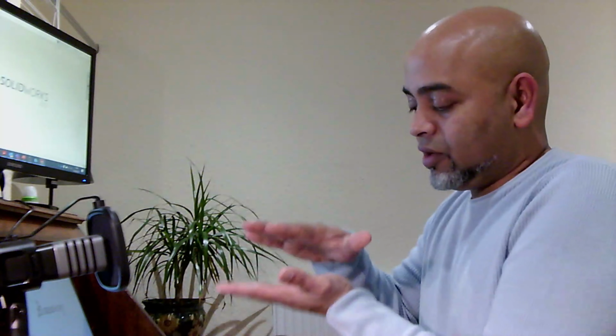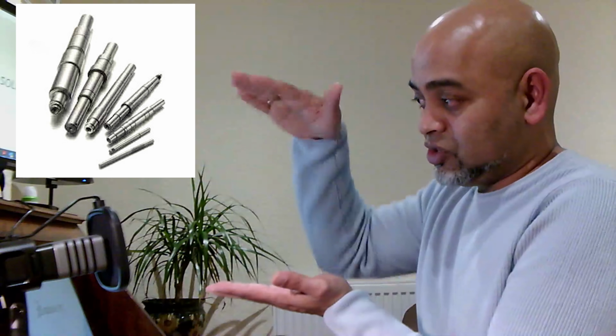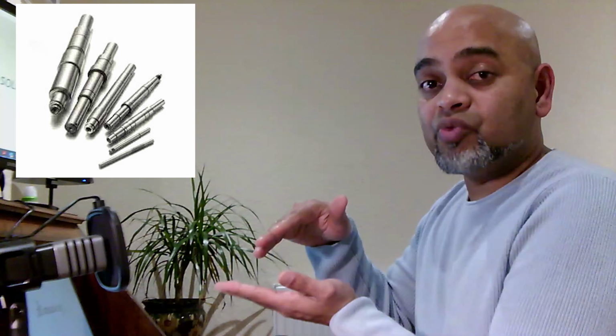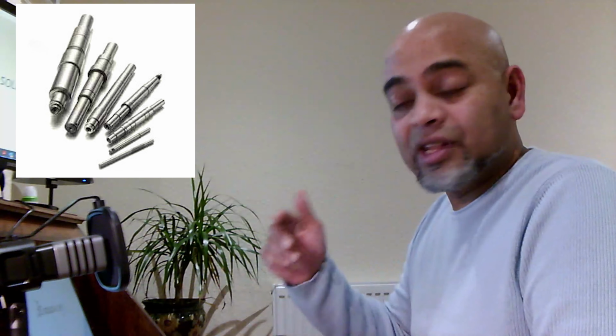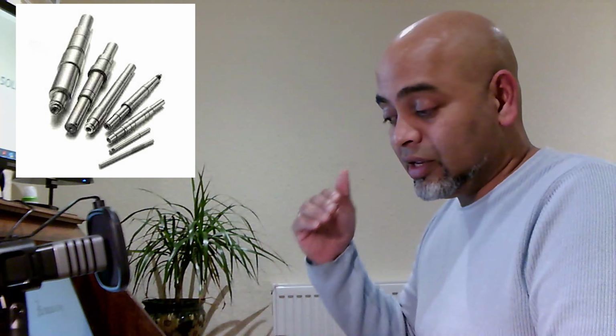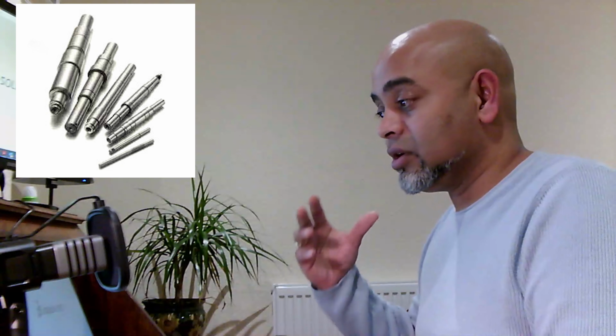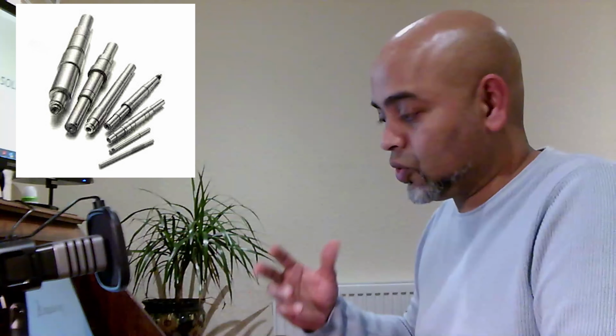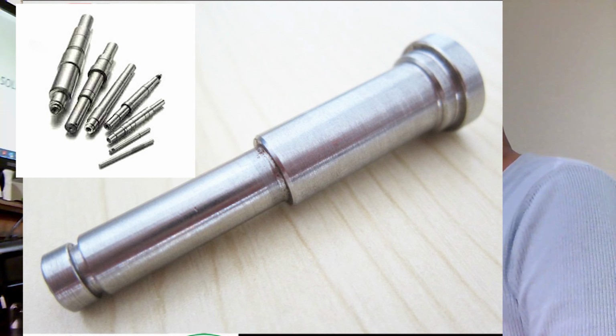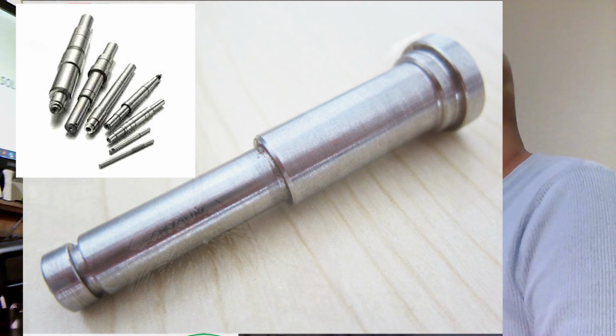Okay, the first step, we're going to start with revolve boss base. In situations where you think I can't specify a cross section and extrude things out straight in this direction or the other direction, that's when revolve is really handy. It's also more efficient than extrusion in cases where you have circular spindly objects. Some of the examples are now shown on the screen where I would think this is an ideal scenario where revolve boss base is applied.